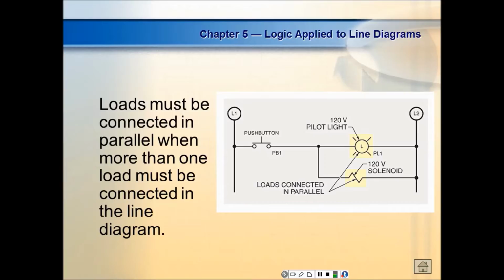And what we do over here on the left, we put line numbers. And of course, they could start anywhere, but right now we'll start them with the number 1. So this would be line 1, that would be line 2. So in motor controls, we don't number rungs, we number lines. In PLCs, if you take PLCs, you'll number rungs. And a rung could have multiple lines, and it does.